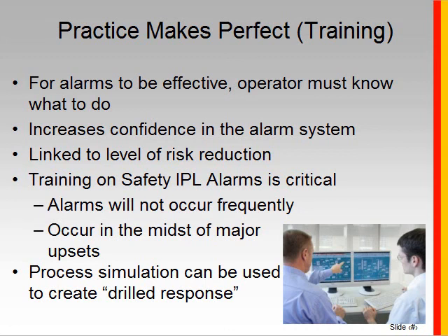Now, of all the alarms that you want to pay attention to for a training program, certainly safety IPL alarms have got to be some of the most critical, because they're not going to occur very frequently, or hopefully not very frequently, and when they occur, it's typically going to be in the midst of a lot of other things going on. So during a significant process upset, you'll probably have a lot of alarms, a lot of people in the control room. So the more training that the operator has had on how to respond to those safety IPL alarms, the better his response will be, and essentially effectively keeping that low PFD value.